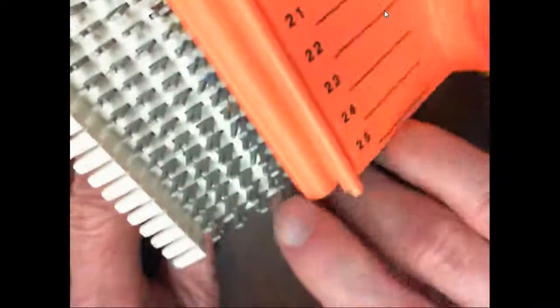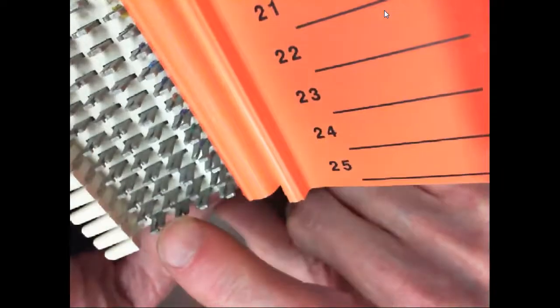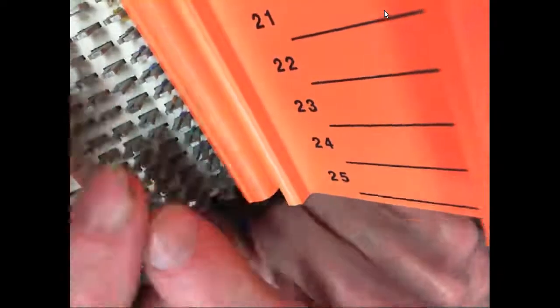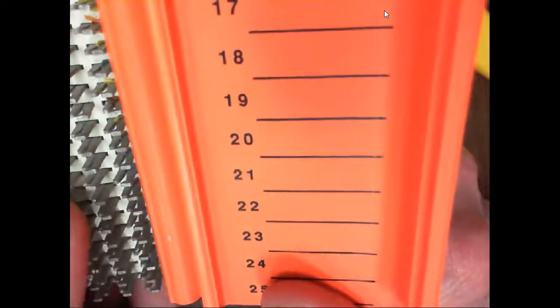So what we would do is we bring the cable into one side, into this terminal. This comes up into these punch down blocks right here, and then we would punch into these depending on which route we wanted to go. Now this is going to be twisted pair cable, so the twisted pair cable would come in on the other side, right? You understand? And it would come through these grooves and go into this punch down.